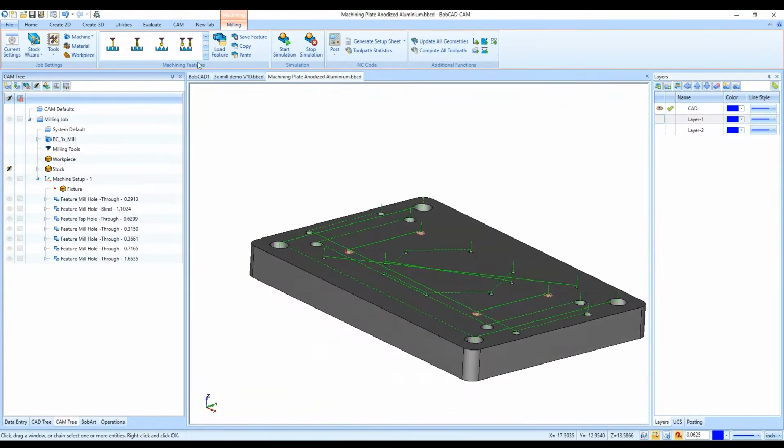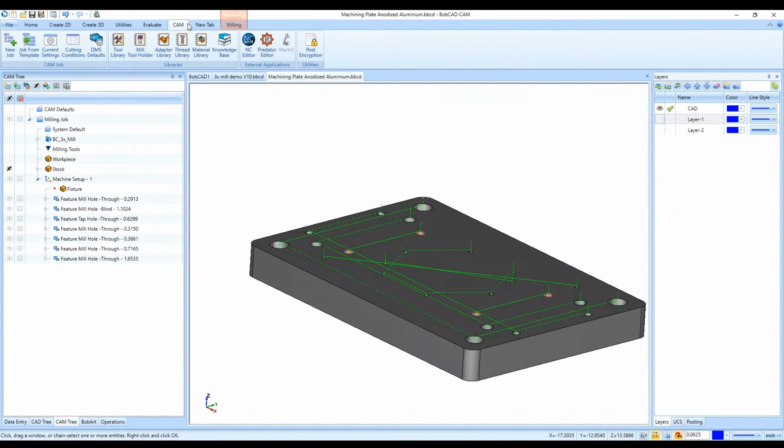And that is at the top under CAM. You can click on this icon of 3 books, it looks like, called Knowledge Base. You'll click on that icon. And this is called the Knowledge Base Manager, where you can set different, what they call templates, and you can set rules in each of these windows here, whether it's for drilling, for counterbore, for tapping, or for counterbore tapped. For example, tapped, I'm sure we'll have something along the lines of drilling, chamfer, and then tapping here.